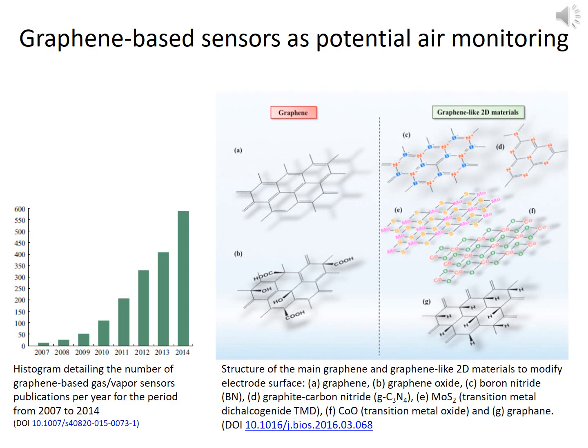An acetylene gas sensor was obtained by synthesis of zinc oxide-reduced graphene oxide hybrids loaded with silver, obtaining a low detection limit of 1 part per million, a rapid response of 25 seconds, recovery of 80 seconds, and good repeatability.